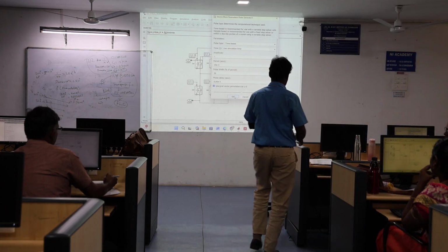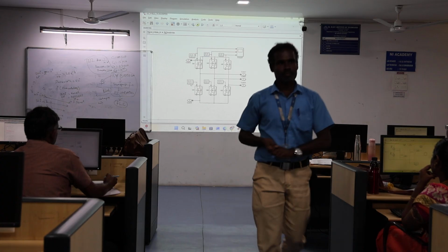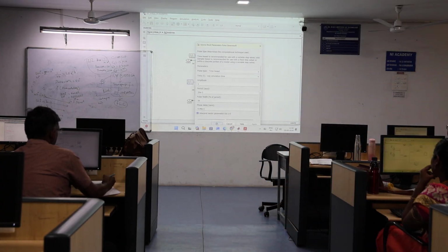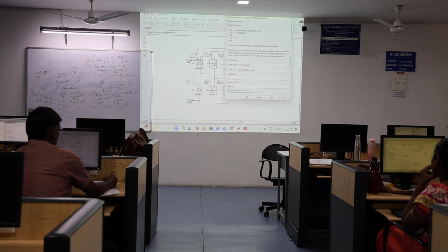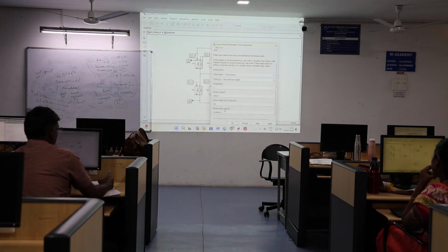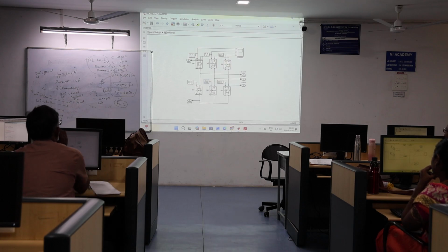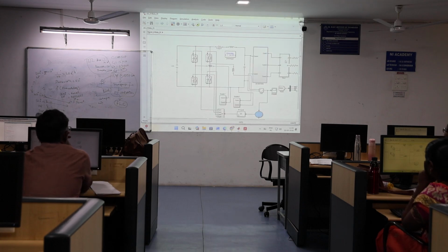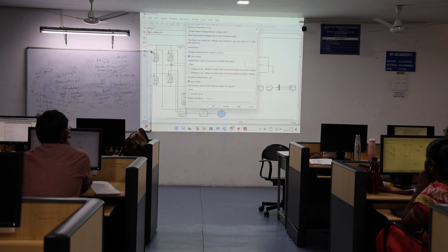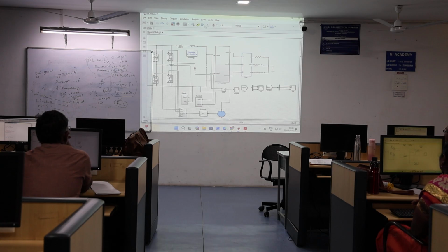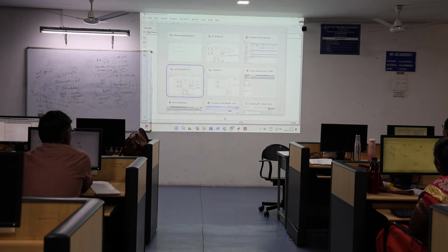Actually every time it will add 3.3 millisecond. When I go with my fourth switch, it is around 9.9 millisecond, for the fifth switch my value is 13.33 millisecond, and for the sixth switch my time delay is 16.66 millisecond. This is the way I put my phase delay, and I have 3 outputs, and for the 3 outputs I have 3-phase measurements. In the 3-phase measurements, I have to choose the signal label VABC, IABC like this. After choosing this, I will get a label. So if I run this program, once again, this is not connected, so show.